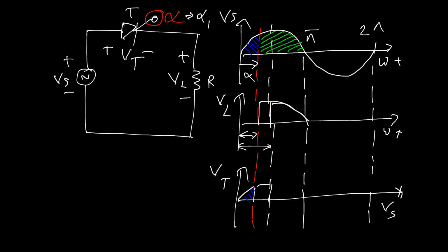We know a thyristor can be switched off by reducing the anode current below the holding current, and that can be done by applying reverse biasing across the thyristor. The same thing happens with this kind of AC signal. After crossing pi, the current is 0, and we are still applying reverse biasing as in a normal sine wave.